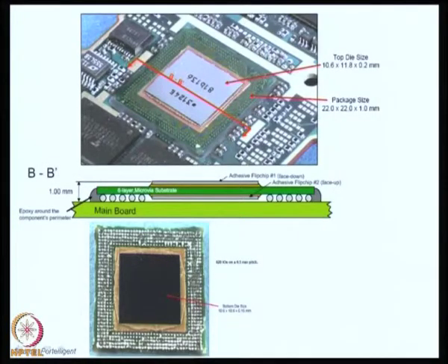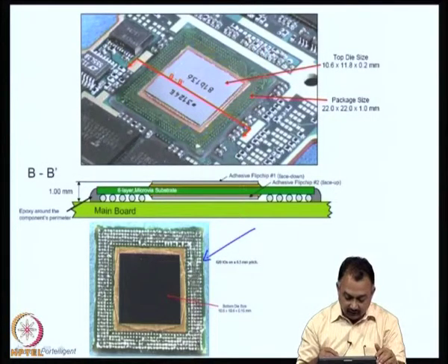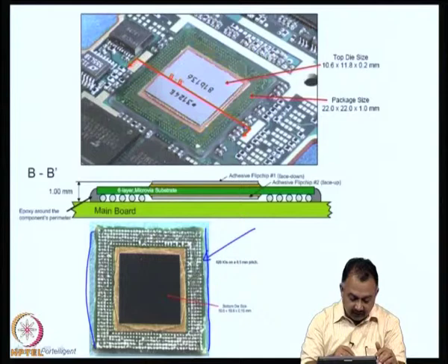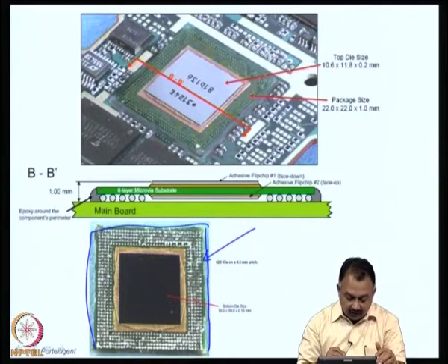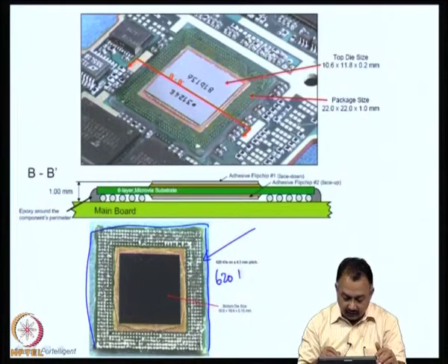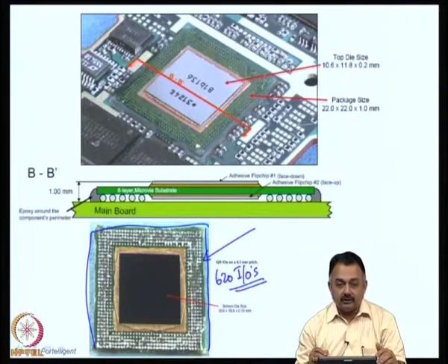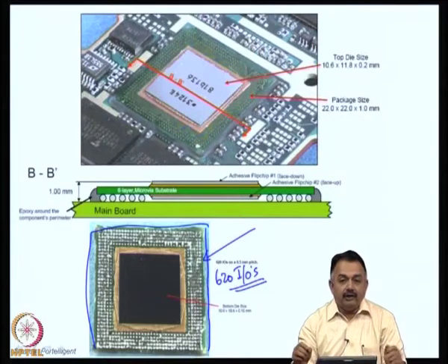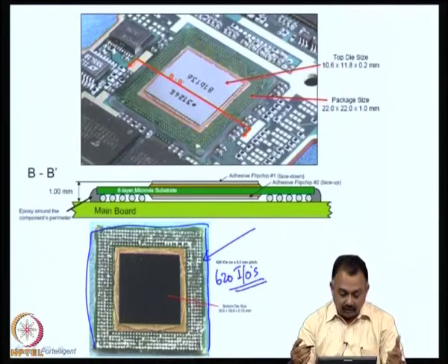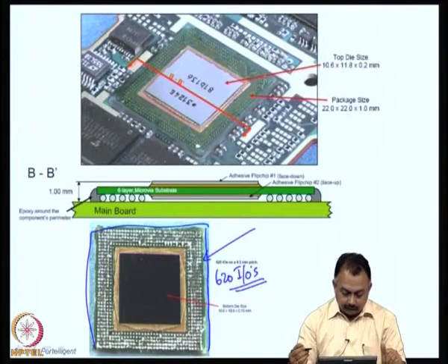This is an example of the solder ball array. As you can see, a series of solder balls here. Okay, it is occupying the entire area under the die. This is the die, and you can see there are 620 IOs in this particular example. So, which is very large. Okay. So, there are FPGA modules today which come with 1200 IOs, 1200 pins, which you have to handle efficiently without even a single error during assembly.